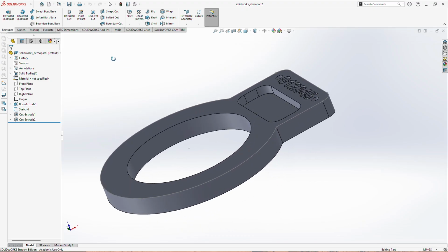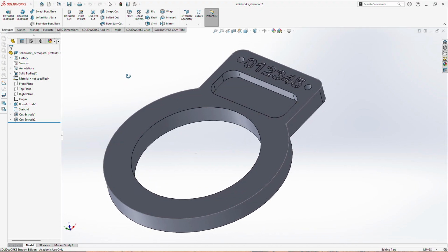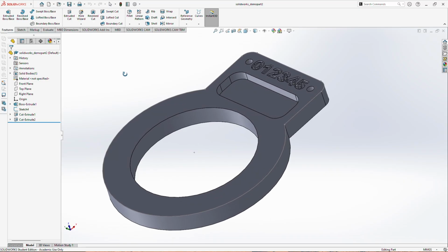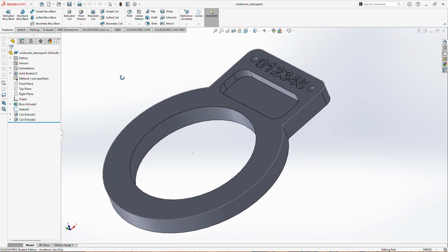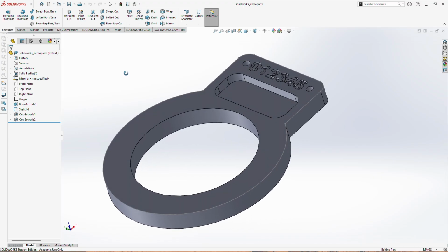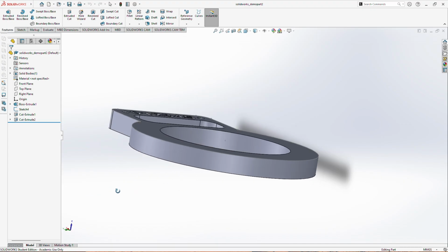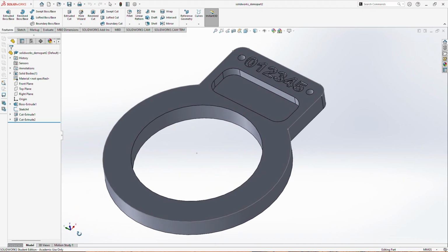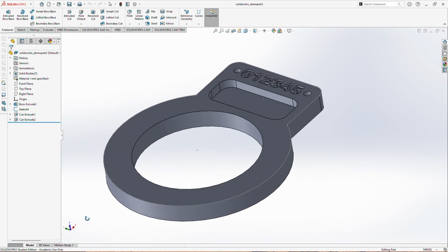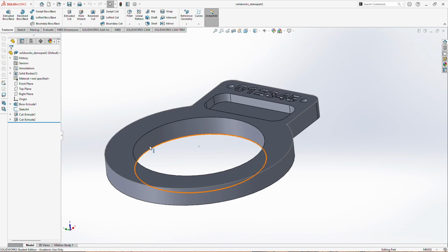So once you've opened up a sample part, we can go ahead and prepare this for manufacturing using SolidWorks CAM. Of course, as mentioned earlier, it's important that you set up the Carvera and all your tool parameters, as shown in the first part of our Getting Started with SolidWorks video series. Also, you'll notice that this part has been designed with a Z-up coordinate system, which is not the default for SolidWorks. Typically, the Z-forward coordinate system is the default, but whenever you're working with a mill like the Carvera, we usually design with Z in the vertical axis.